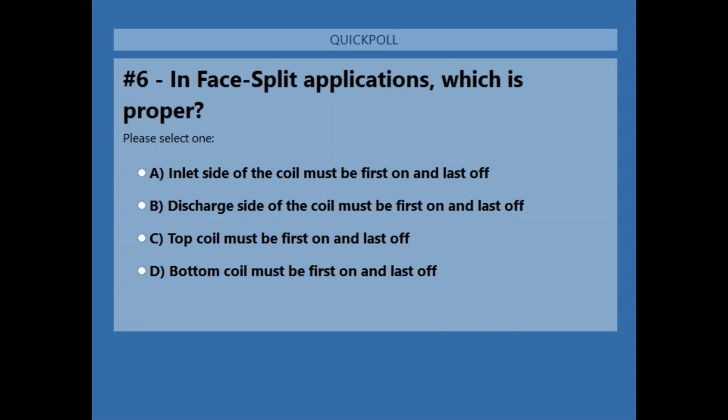We can drive up to 4 solenoid valves with 38 APDs. Typically you use 1 or 2, but in larger jobs, we need to shut off part of the coil at low load so we have proper velocity through the coil. So you may be up to 3 or 4 liquid line solenoids. So it's really dependent upon the evaporator section you have and its size and tonnage of equipment. But we'll say 1 to 4.